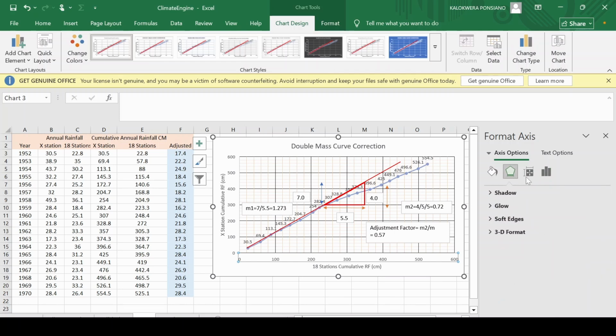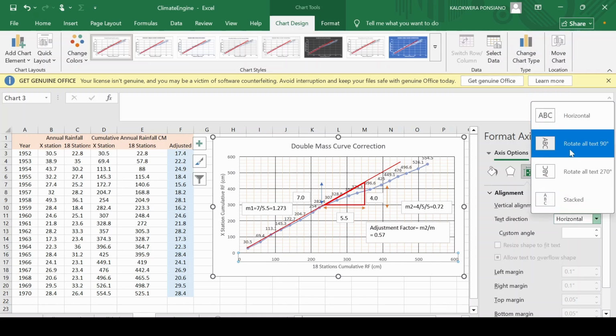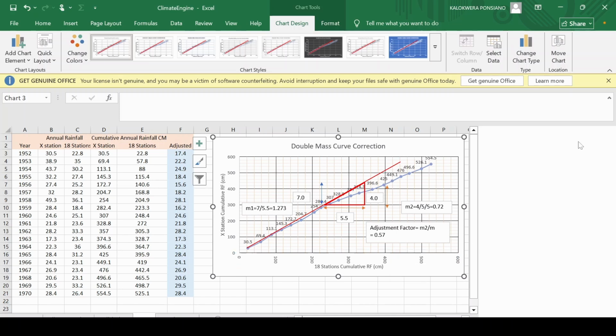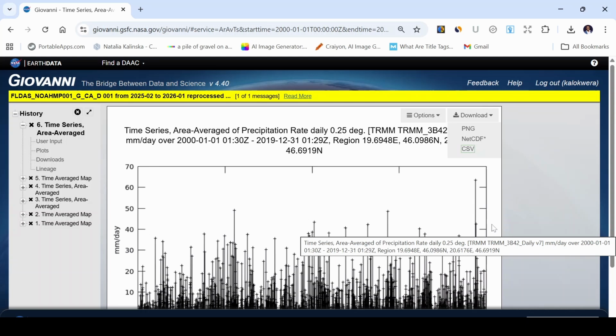This really helps to connect data to real engineering outcomes. So once validated, TRMM data informs decisions such as catchment runoff estimation, design storm selection, spillway capacity, and safety factors. As you know, rainfall data does not design structures. Engineers do. So even after validation, I apply conservative judgment. I make sure I take care of the factor of safety, do some sensitivity checks on the corrected data, and also perform a detailed design review.